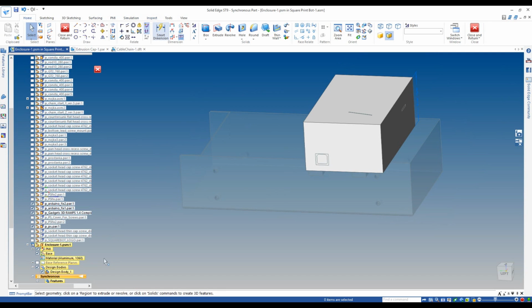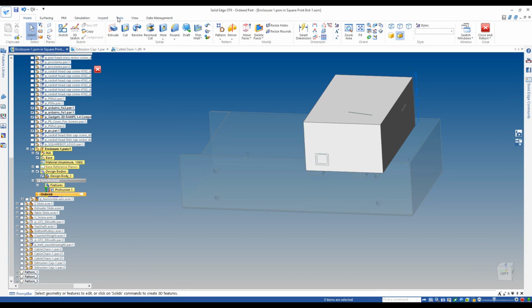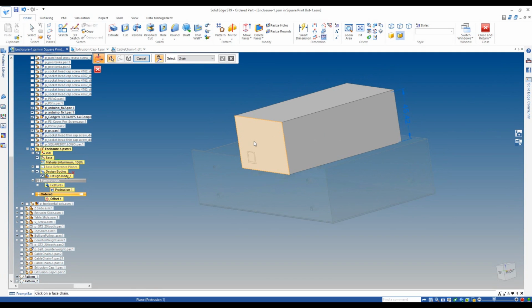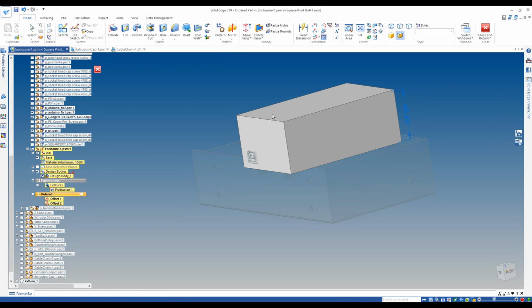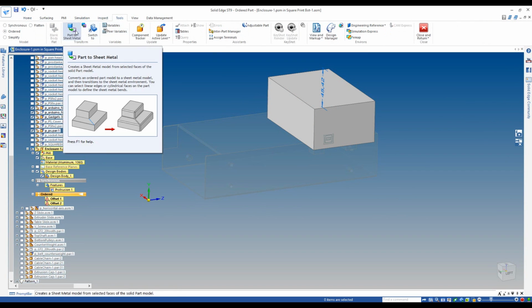So next I just come in and I say that I want to actually convert this whole body. But before I do it, I should actually add some clearance. So I'll add clearance onto the sides I want clearance for. Specify how much clearance I'm adding. And I may even move this face back a little bit so that that connector will poke out from the enclosure. So I specify that. That's all good. And I'll simply come and convert this into a solid.